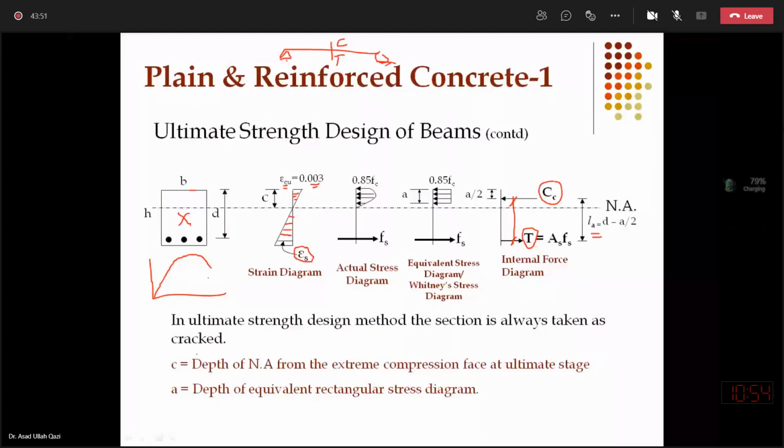So this will be the total stress-strain curve, which has been rotated by 90 degrees and is present here above the neutral axis. So the top fiber, which is at 0.003, has softened, and it is this point. And a fiber which is a little inward at this moment will be at the peak, which is this one.